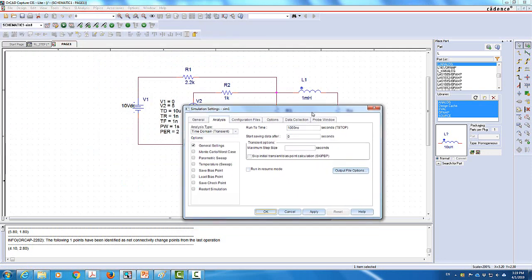I'm gonna basically run the simulation up to 20 micro. So 20 micro is really a good number, because we know that the time constant for the circuit is 1.14 microseconds. Then actually we are running the simulation for roughly 15 times tau. Usually we assume that we reach infinity for t greater than 5 tau. So around the 7 microseconds we assume that's infinite. 20 microseconds is actually way more than that.